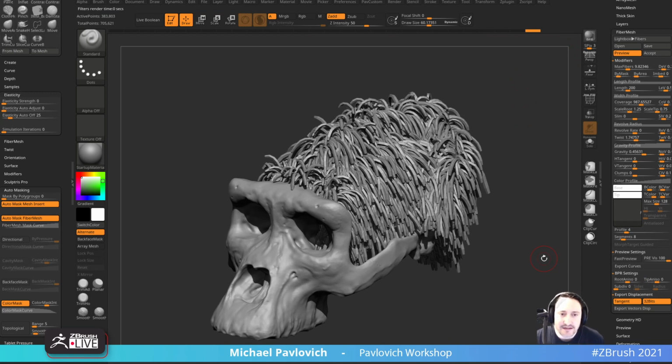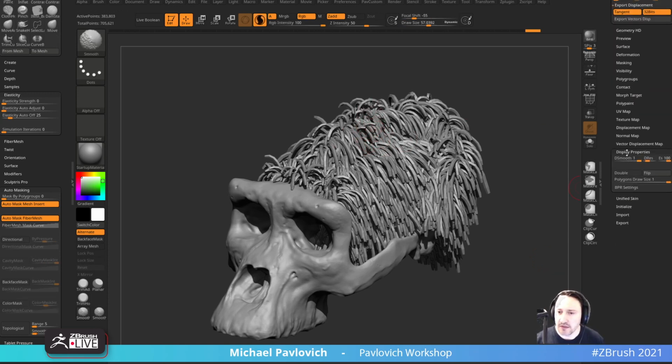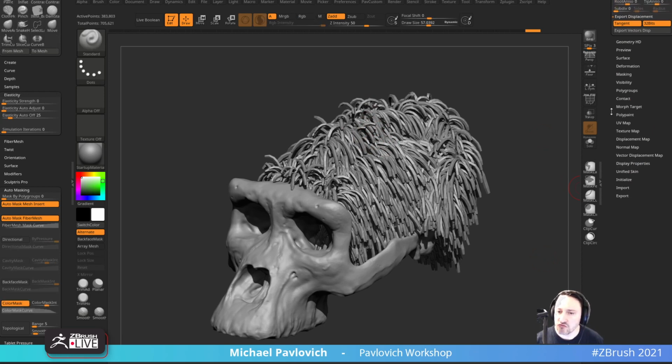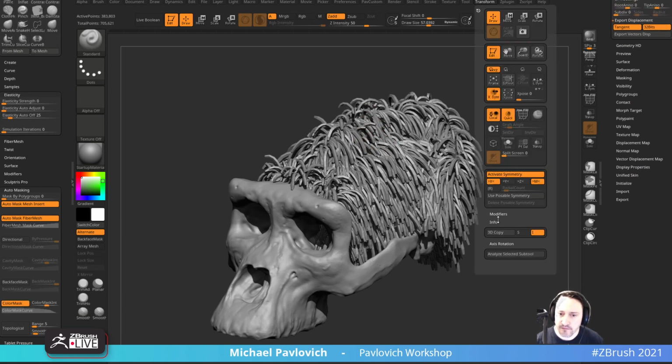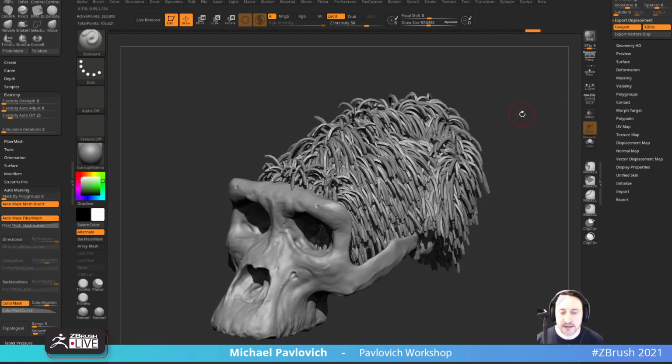As far as getting this to print correctly, you'll have to do some work with probably Dynamesh, and then also mix in a little bit of this transform draw draft analysis, because you're going to have a ton of undercuts in there. So I don't know, it's not super fun to clean up. If you want more information on draw draft analysis, I think that was ZBrush 2020 What's New.